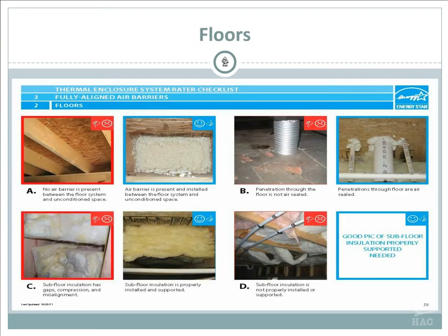So the first one you see has no air barrier, and it doesn't continue back in there. This should have been sealed off right here at the far left corner. Here's one that is sealed. It's blown in with foam, and it seals off that far end back in there. So when you're spraying your insulation, you're not filling that soffit with insulation. You're stopping right there over that 2x4.